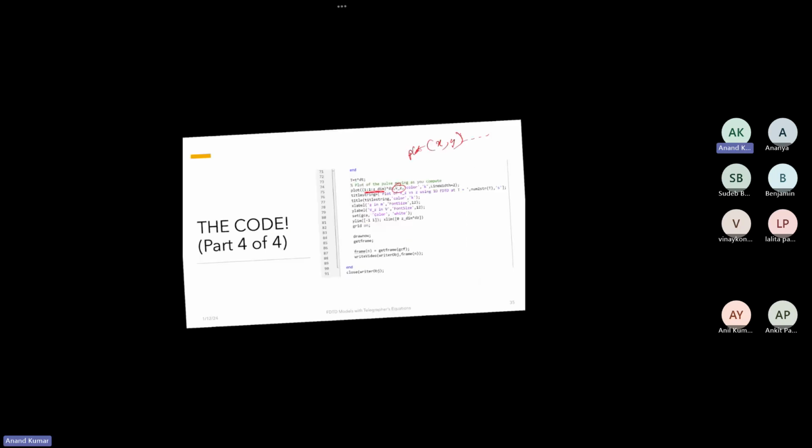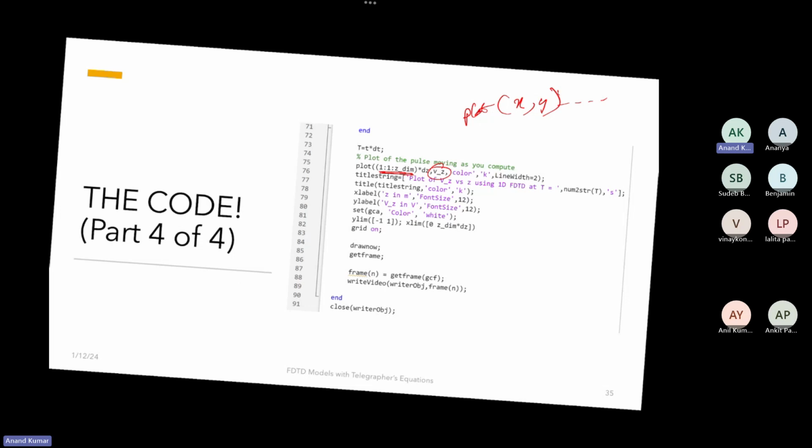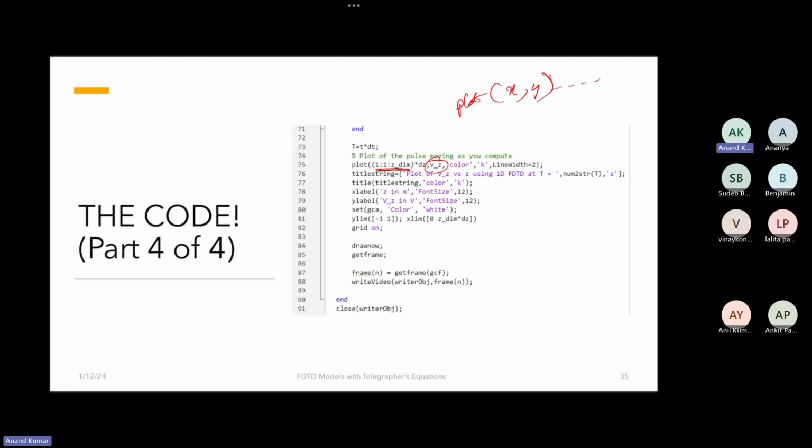The x value is basically the length of the transmission line if this is your simulation space, and the v value throughout the simulation space gives you the voltage value at each instant, showing one particular picture at one time instant. Since this entire plot code is inside the for loop, this plot updates at every time instant, and you see your Gaussian pulse moving forward.